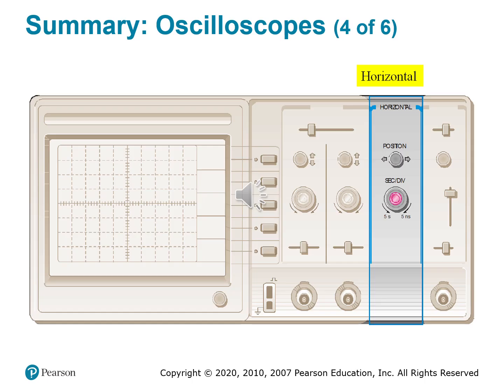So, the horizontal position knob lets you shift a waveform from left to right, adjusting where the trigger point lands or aligning multiple waveforms for comparison. What else? Yeah, this is especially useful when you want to compare signals from different channels, capture specific segments of a repeating waveform, and analyze the pre-trigger or post-trigger behavior in single shot captures.